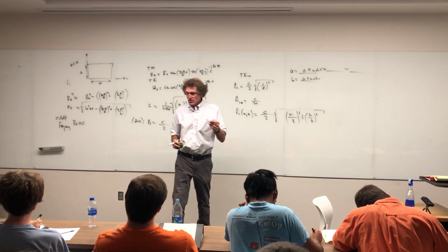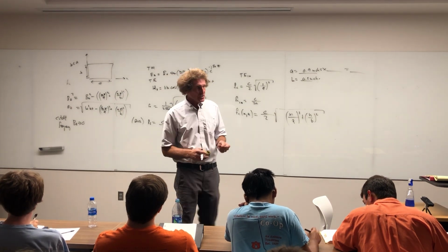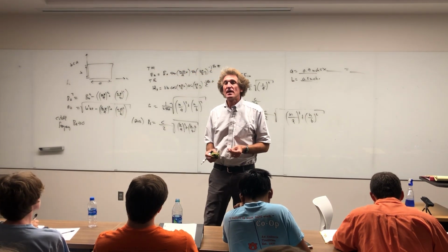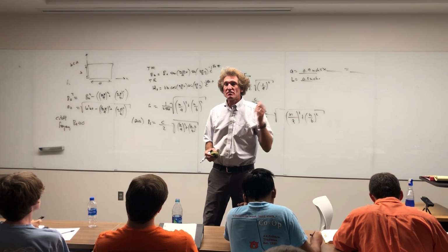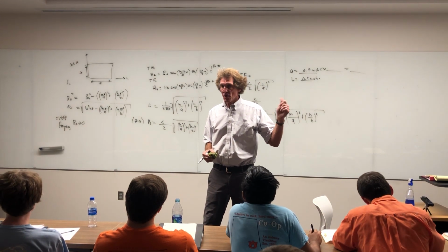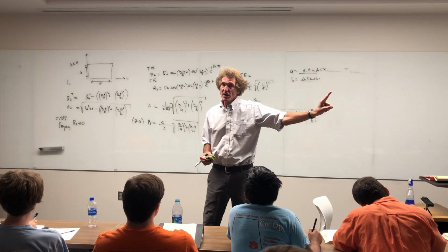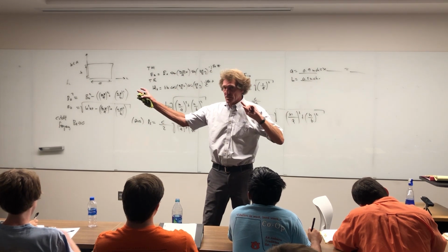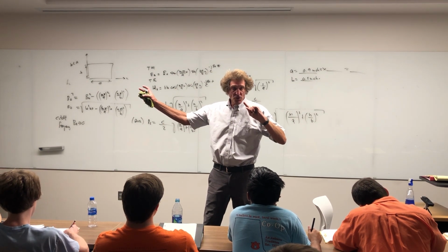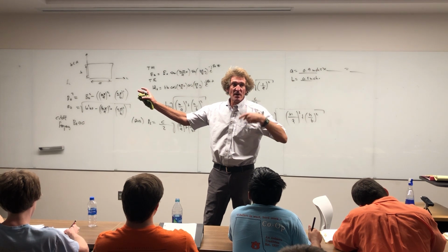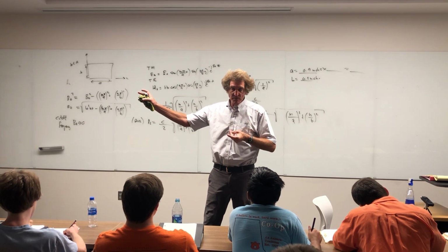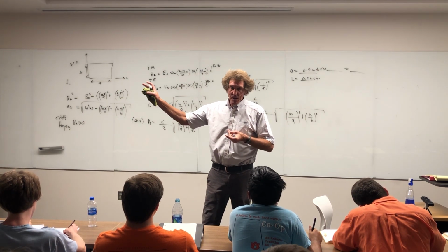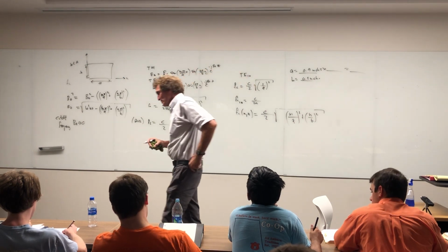Now remember, what was the real thing you wanted to know when you had transmission lines? What was the key thing? You wanted the characteristic impedance, right? You wanted to know what the load was, and what the source resistance was, and then you could easily calculate the standing wave ratio and anything like that before you did matching. Do you all agree with this, class? Most of the time with waveguides, you don't do impedance matching.